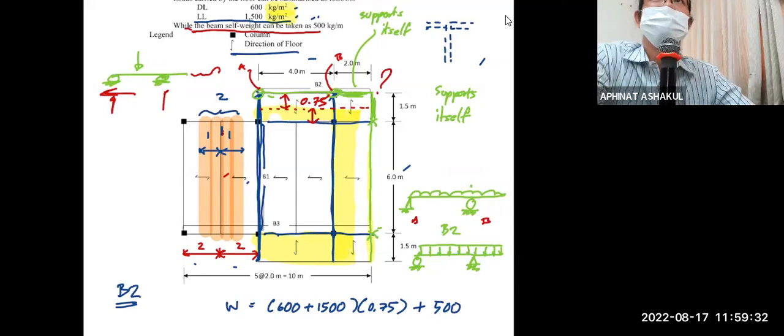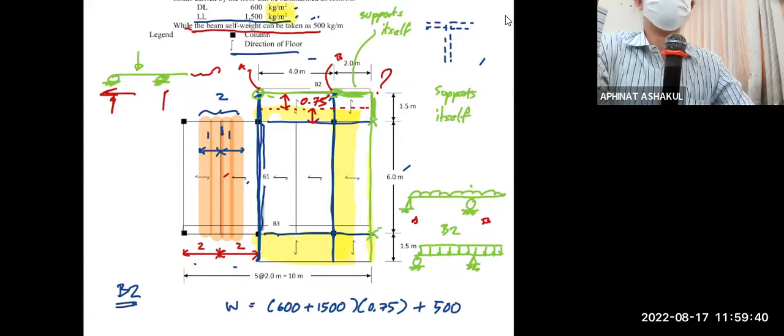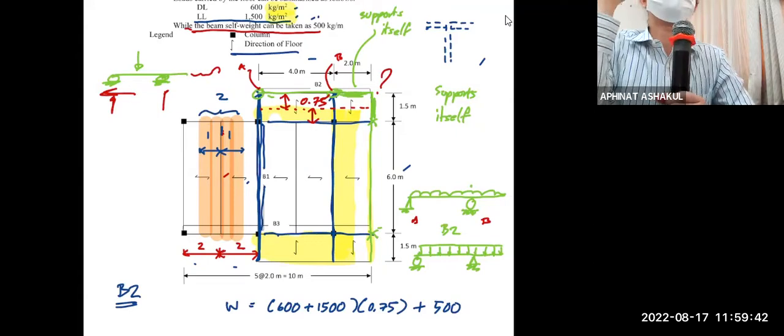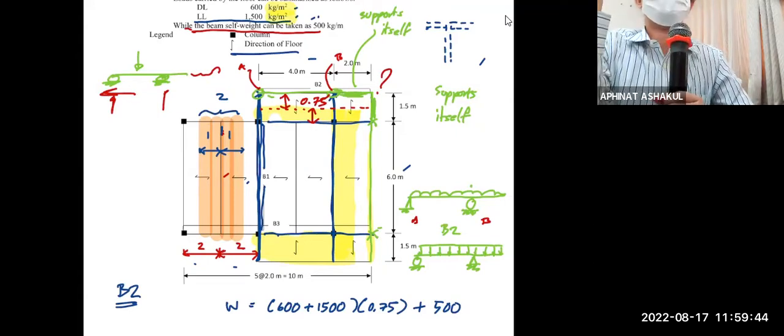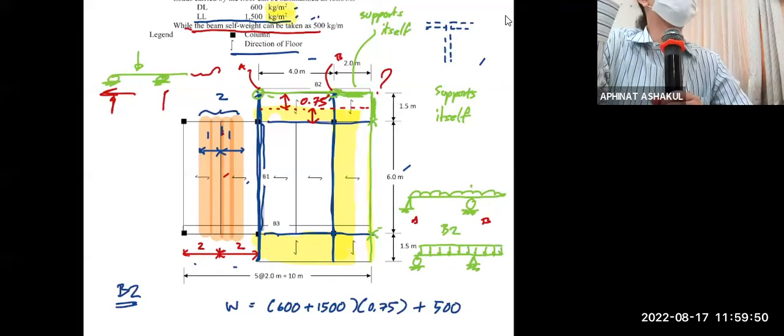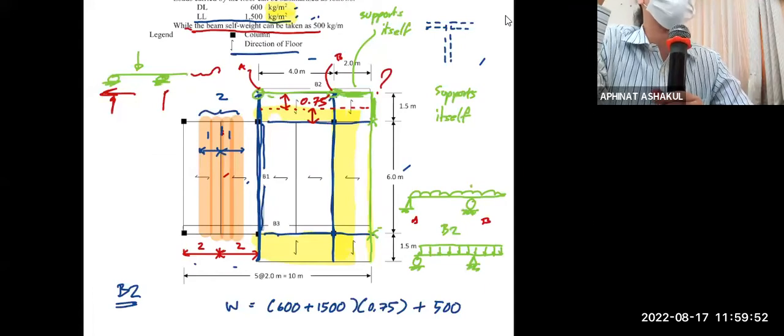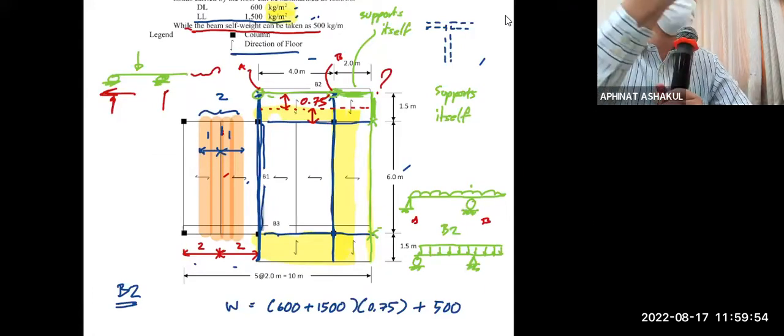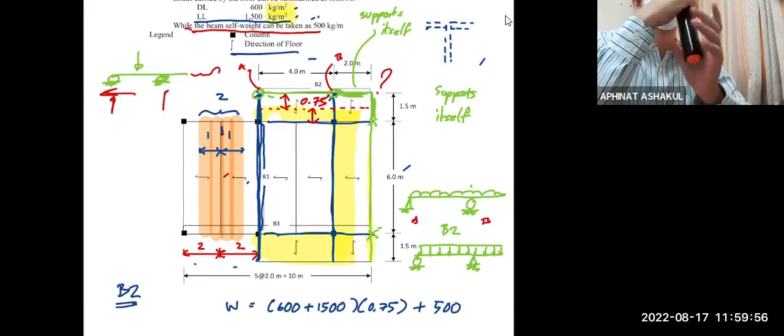So that's the unit, so it can be added together because they have the same unit, right? Now be careful. Sometimes when you're dealing with the system, there can be walls. And some beams will also have to carry the wall. So you need to check with the architectural plans, okay? In this case, we don't have any beams that carry the wall, so that's great.